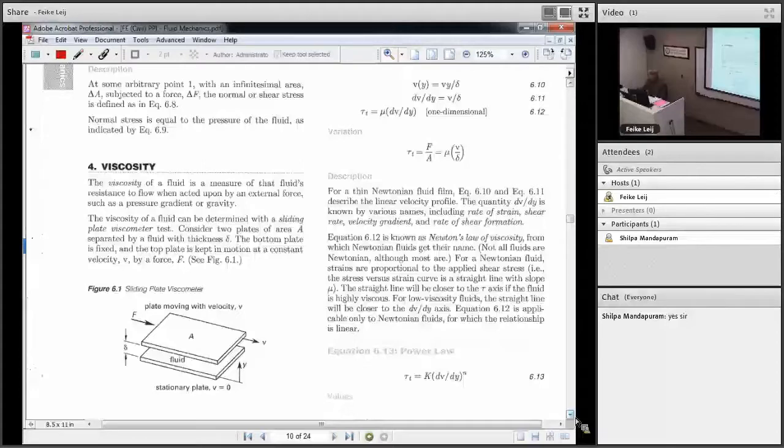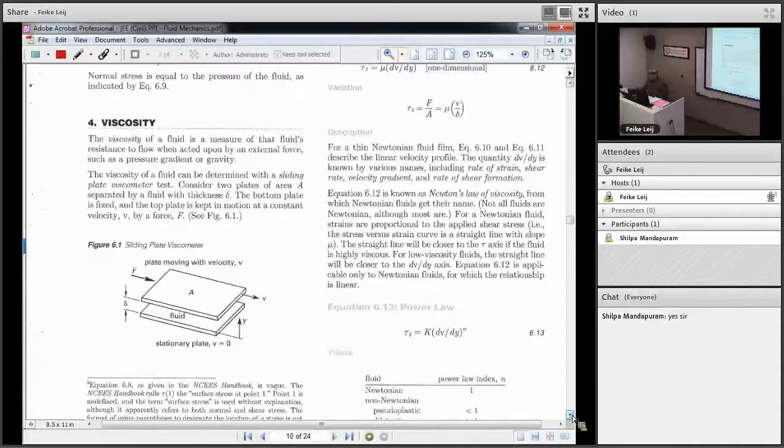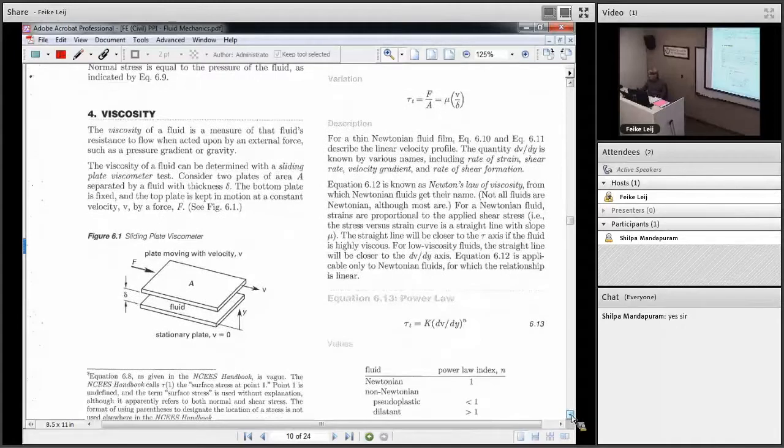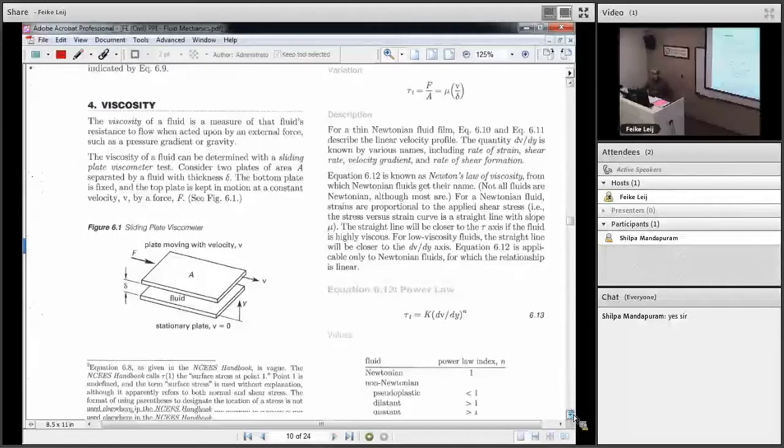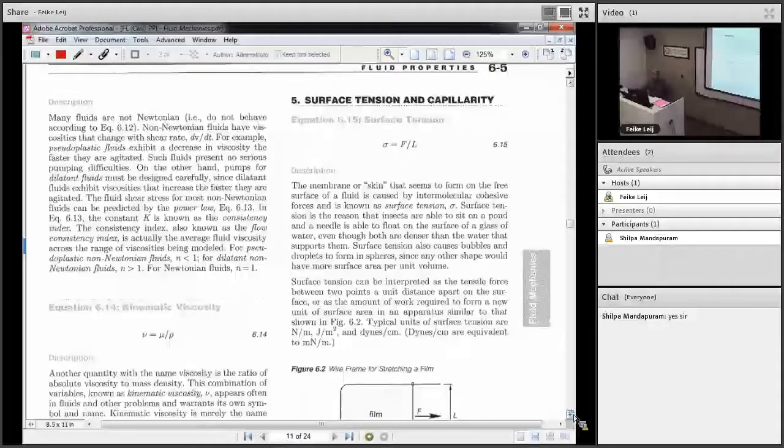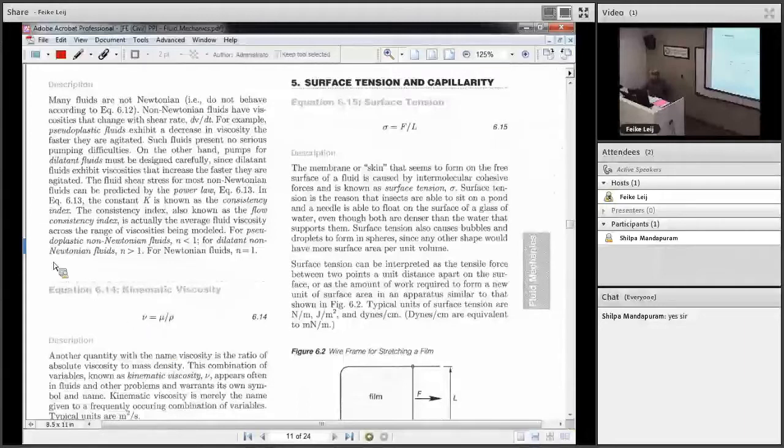Now, not all fluids are Newtonian. For example, paint and certain starches start to react differently depending on the shear stress, and we don't have a proportional behavior. Now, in fluid mechanics for civil engineering and mechanical engineering, we're typically not too worried about it. We often assume Newtonian fluid, but for the folks in chemical engineering or dealing with food, they really have to pay attention to non-Newtonian behaviors.